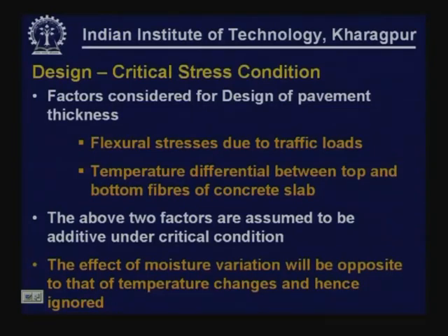The critical stress condition that is considered in IRC 58 2002 takes into account the factors considered for design of pavement thickness, as we discussed earlier: flexural stresses due to traffic loads, temperature differential between top and bottom fibers, and resulting curling and resulting temperature stresses. So, these are the two stresses that are considered. These two factors are assumed to be additive under critical condition. Critical conditions would be during noon time, when both the curling stresses and wheel load stresses will be additive.